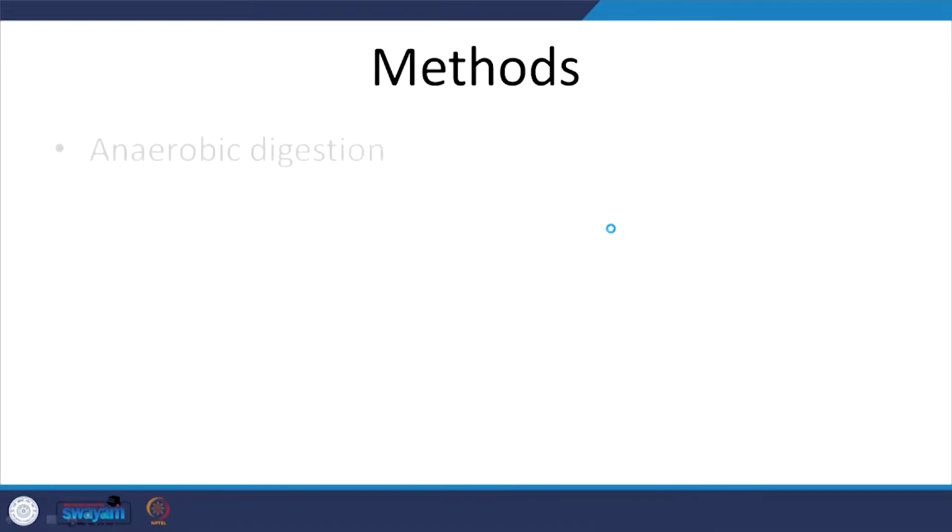So, different methods. One is anaerobic. Firstly, why anaerobic? And again note that this is widely used. Sludge, especially the organic sludge here, has a lot of organic concentration. So, if you want to do it by aerobic, you need to provide oxygen. If you are doing it within a controlled system, yes, that also can be done, but again you need to put in energy, right.